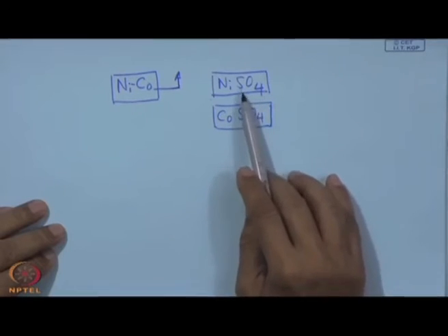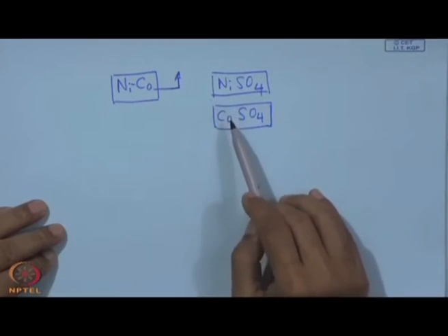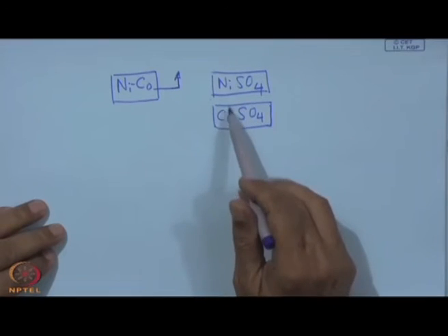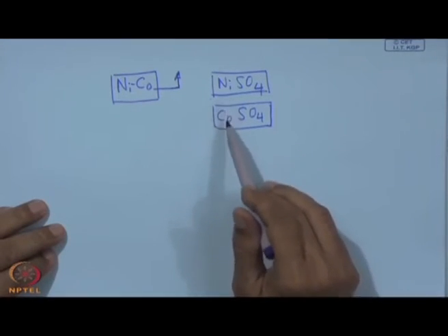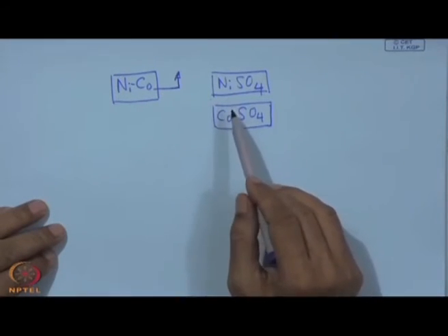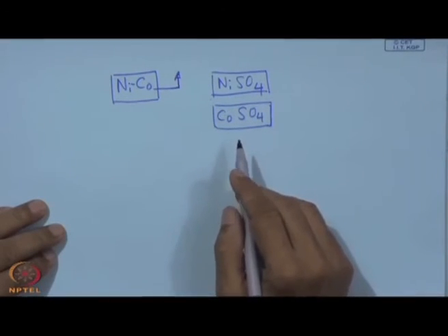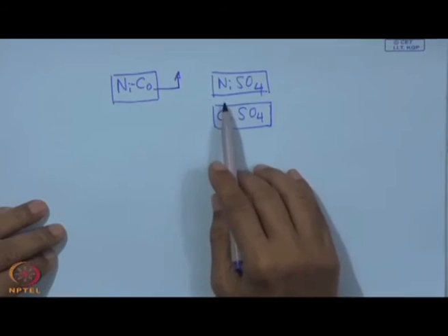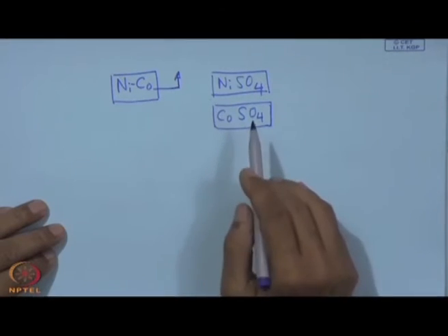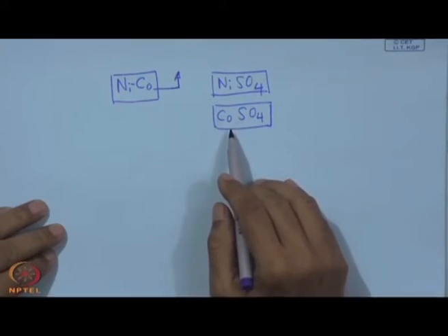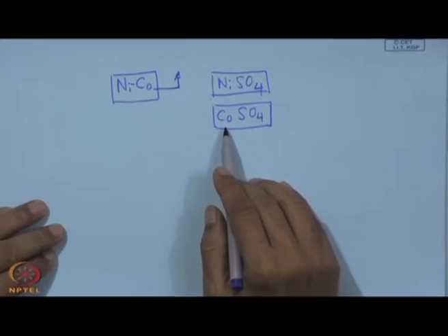It depends on the electrochemical equivalent of nickel and cobalt, and also their respective concentration, and accordingly we have the deposit with certain variation in their percentage, but in principle co-deposition by this galvanic technique is also possible.